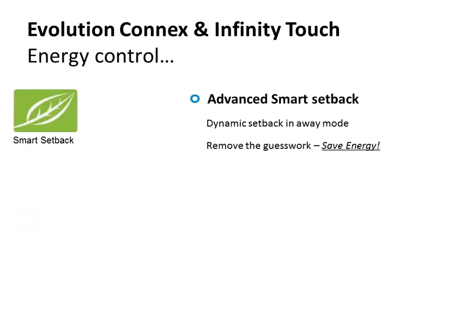It does have a pretty cool energy tracking mode. Excuse me, it has energy tracking mode, but right now I was going to tell you about the smart setback. What this does is not only does it do the typical smart recovery where if you say I want to go occupied at 8 a.m., it starts tweaking your set points at whatever, 7:42 or whatever time it calculates it needs to tweak them to get there by 8 o'clock. It does that, but also it doesn't allow the stat to set back too far and waste energy. This is especially useful on heat pump systems that have electric backup heat.